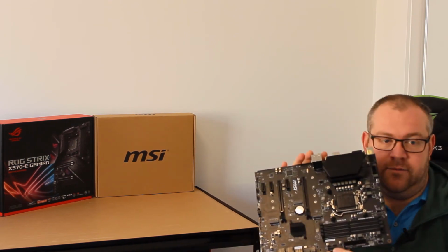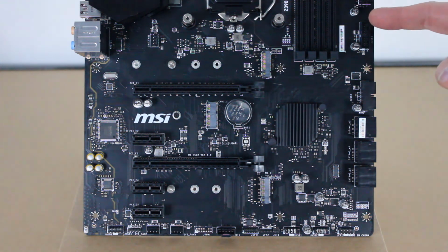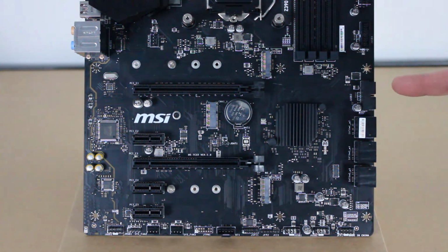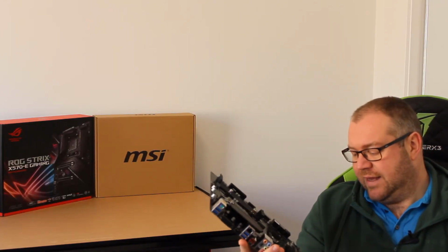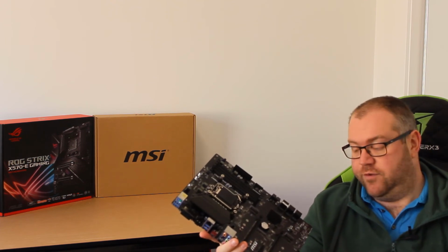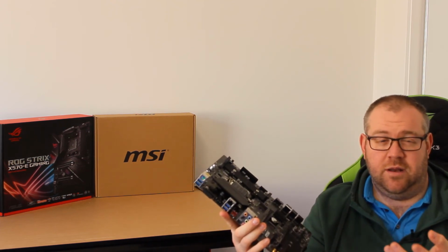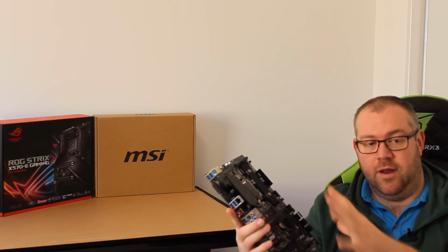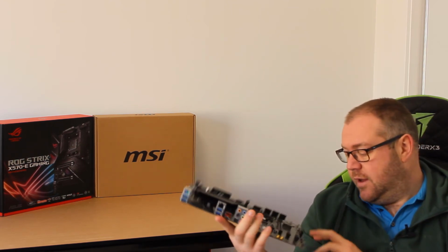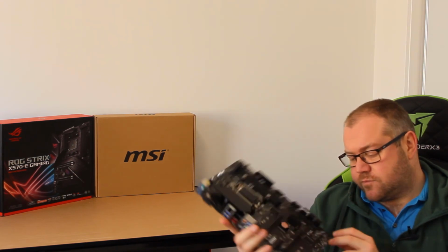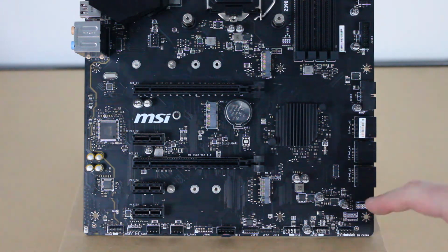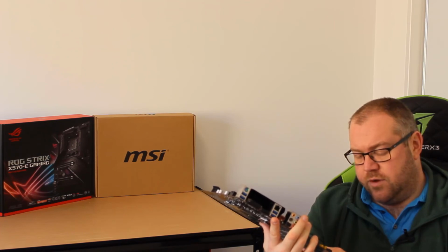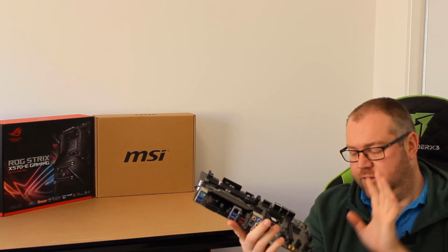So there's a USB connector for your front panel. You've got a USB 3 connector for the front panel as well. And depending on the case, you may need both or just one of those. The case will tell you what to plug it into, as will the board diagram in the handbook. Then you're going to have other headers here. So usually down in the bottom corner here, and we'll get some close-ups of this. Generally, that's the connection for your power button and things at the front.